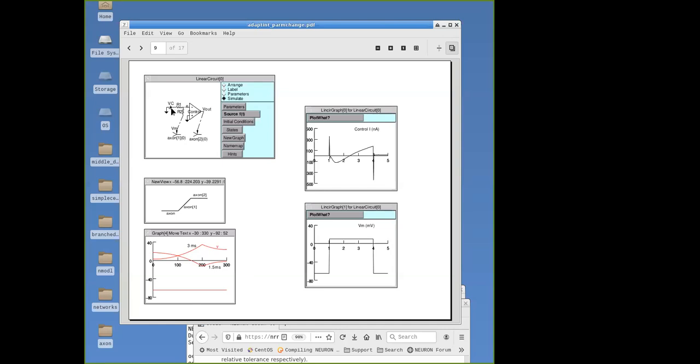We're trying to make the difference between this measured voltage and this command potential be 0. The way we do that is we have a pair of resistors that have identical magnitude. So this is a voltage divider. The potential at this point is halfway between the command potential and the potential here.